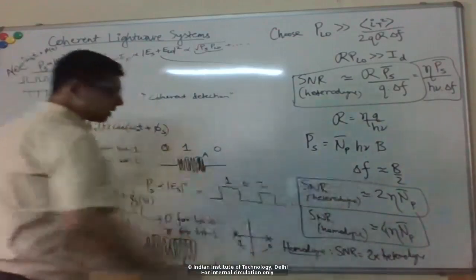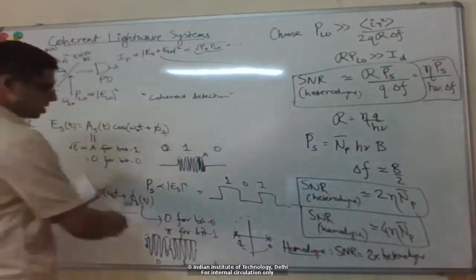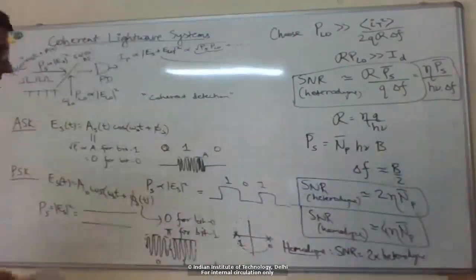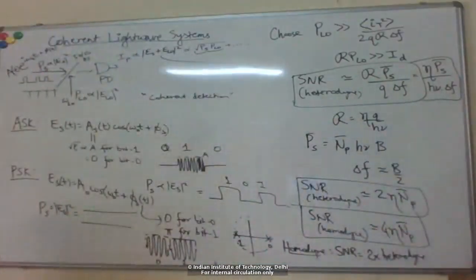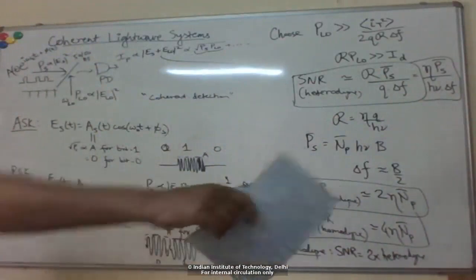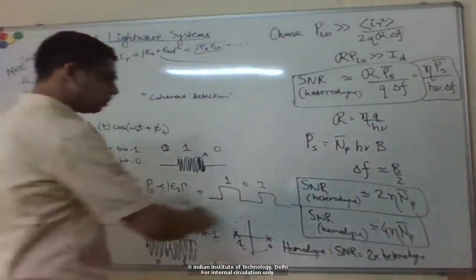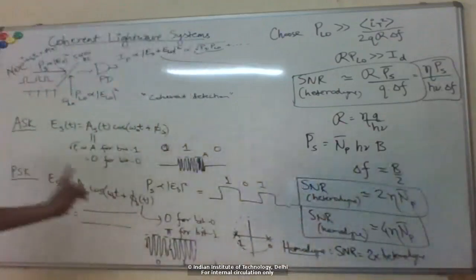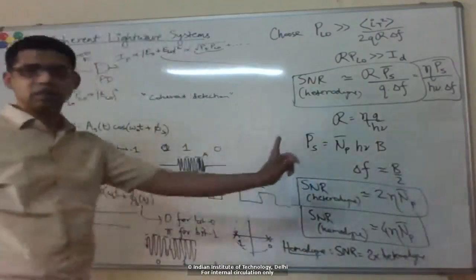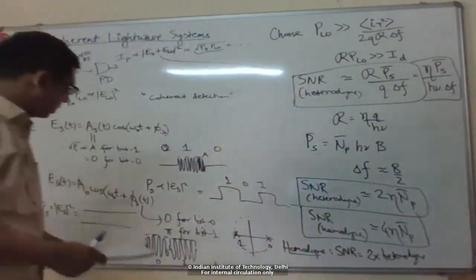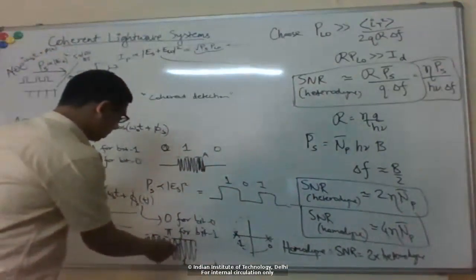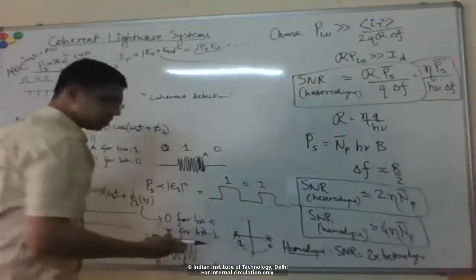So if I have a very long bit stream, my phase has to be stable over that entire bit stream, right? So if I'm sending 10 billion bits, then my phase has to be stable for that entire 10 billion bits. For example, if I have 10 gigabit per second, then I take 1 second to send those 10 billion bits. My phase has to be stable for 1 second if I want to measure the absolute phase for each bit, right? Because if the phase jumps somewhere in the middle, then I don't know if it was 0 and then jumped to pi, or was it pi already.